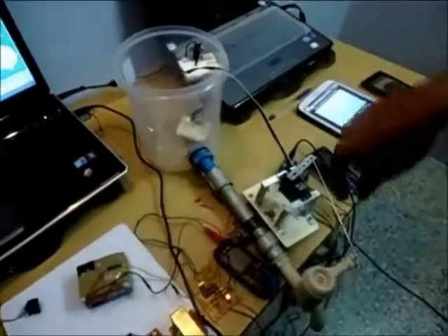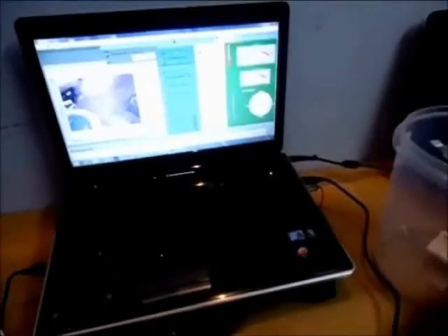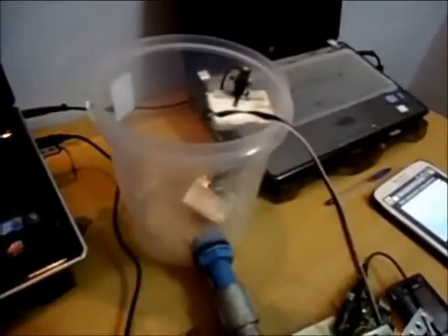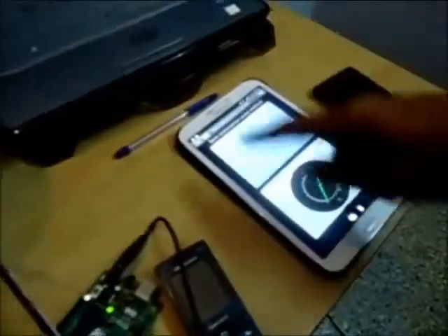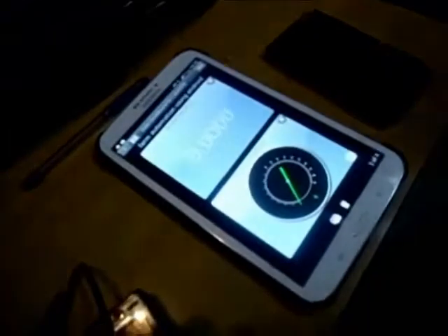The irrigation system shown here can be scheduled, manual or automatic. The scheduled irrigation can be activated as per the requirement of the farmer. The automatic irrigation will be activated as per the soil moisture content. Whenever the moisture content goes below a threshold value, the automatic irrigation is activated automatically. The manual irrigation can be activated using the GUI over the internet or by this Android application.